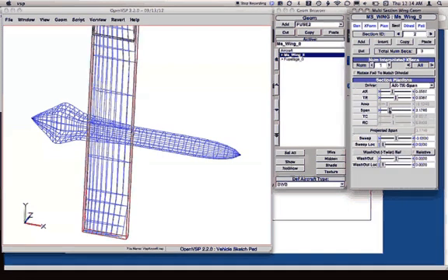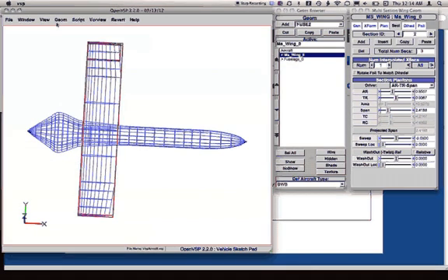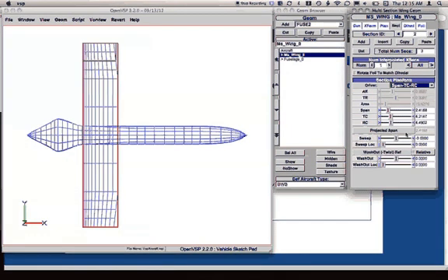not the overall span, I'm going to change the section span in this case for this piece. So we want to be able to change that and then keep that span. Do this from the top here. So for this particular section, and only worry about that particular span. Okay, so change that span on that section. We can add another wing in here for the tail.